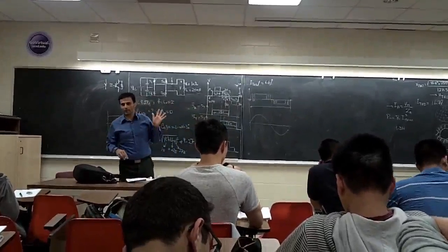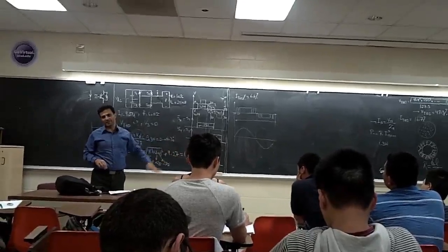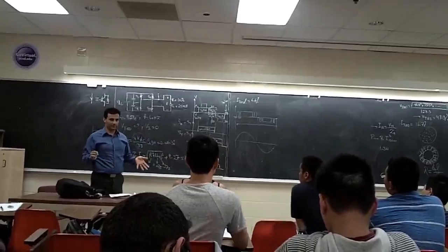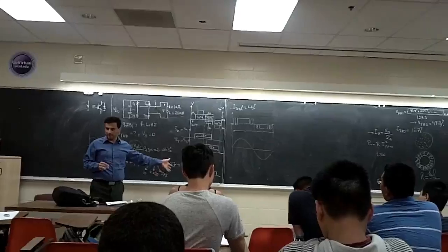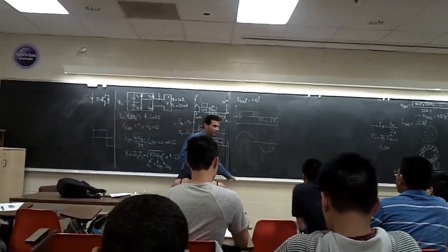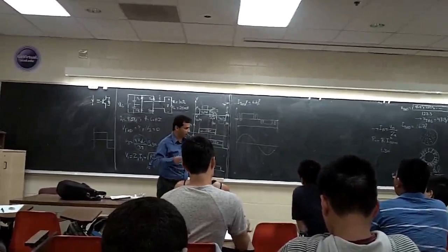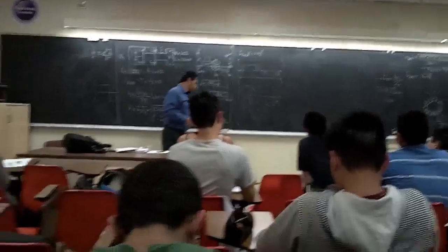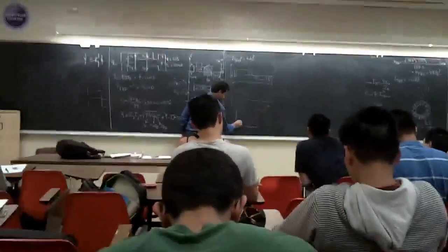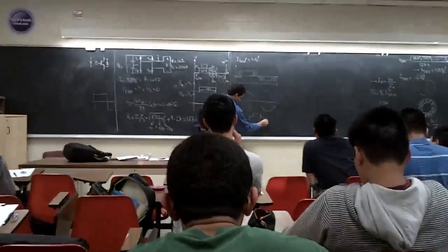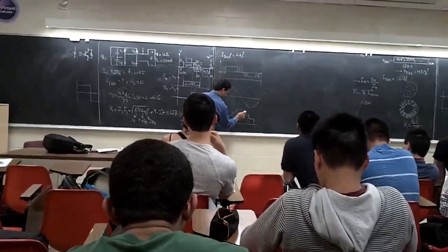Usually when it's very high power, high voltage, you go toward multi-level converters. But even nowadays, for small PVs, they're going to multi-level converters because it gives you much better efficiency. There's less switching. Maybe 5 years ago it was expensive to go that way, but now the price is dropping. With technology advancing, they're going more toward multi-level. Because think about it, if you build this one, maybe this is good enough, right? Maybe 1, 2, 3.